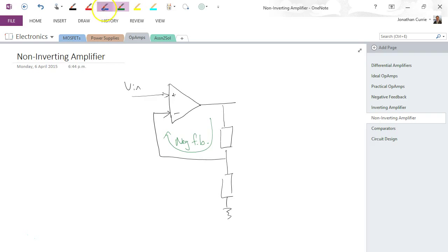In this circuit we have Vin, Vout with two resistors. The resistor in the feedback network I normally call RF, and in this case I'm going to use RI again for the second resistor, and our task is to find AVCL, or the closed loop voltage gain for this particular circuit. Noting once again AOL for the particular op-amp that we've chosen.